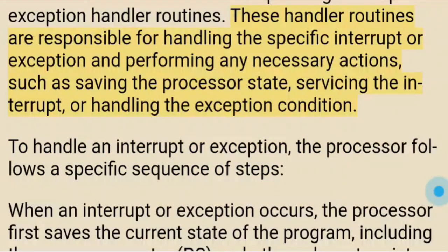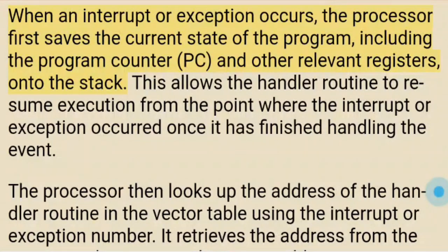These handler routines are responsible for handling the specific interrupt or exception and performing any necessary actions, such as saving the processor state, servicing the interrupt, or handling the exception condition. To handle an interrupt or exception, the processor follows a specific sequence of steps. When an interrupt or exception occurs, the processor first saves the current state of the program, including the program counter (PC) and other relevant registers, onto the stack.